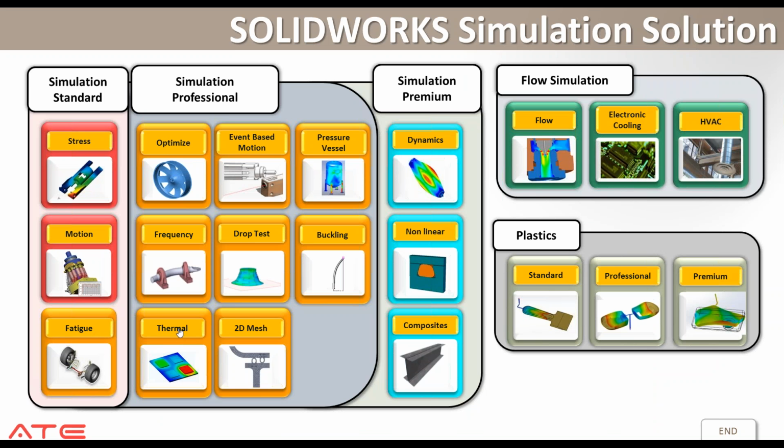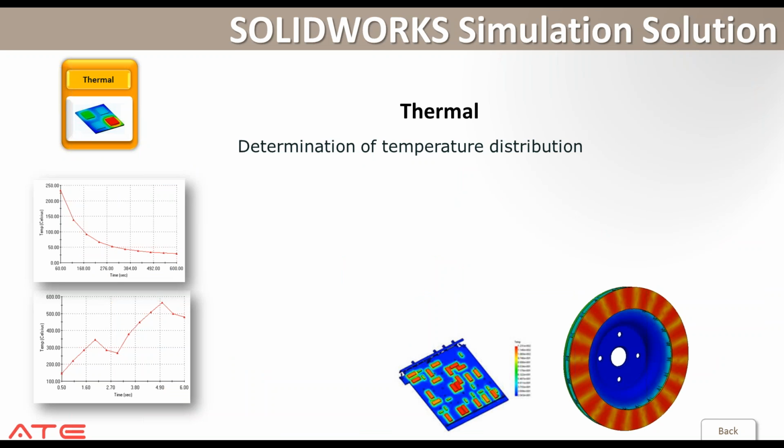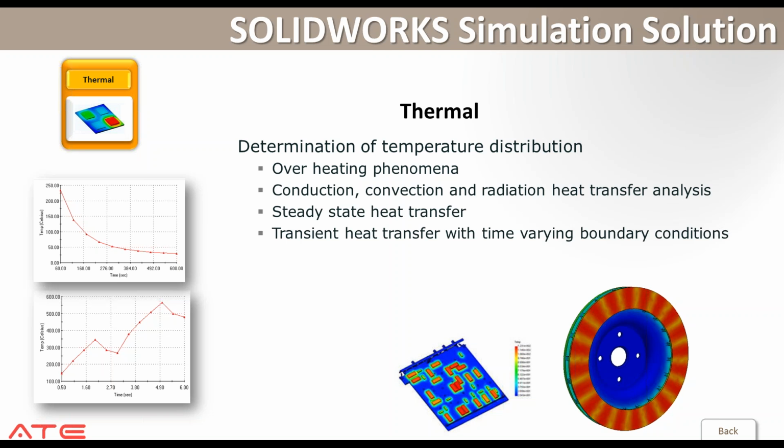Then additionally, we have thermal analysis as well. The thermal analysis in these simulation packages is very highly related to conduction analysis. Also, although you have the capabilities to put in a convection value or the radiation values on the surface of a component, we won't be able to capture the temperatures of the fluids. So it is only capturing the information of a component, and it calculates for steady state heat.